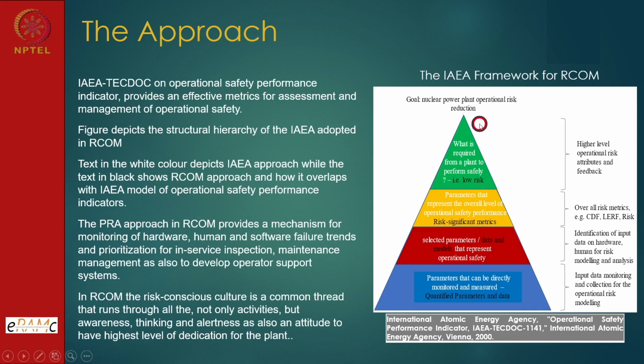So this is the second module. This is the objective function. Then how are we doing it? Risk significant metrics: I have the probability, the core damage frequency, the cut set conditional core damage frequencies, and unavailability statements. So again, it is a quantified risk matrix, the risk significant matrix, and added to that, for each component I have the importance measures: Fussell-Vesely importance, risk reduction worth, risk achievement worth. We can talk in those terms.